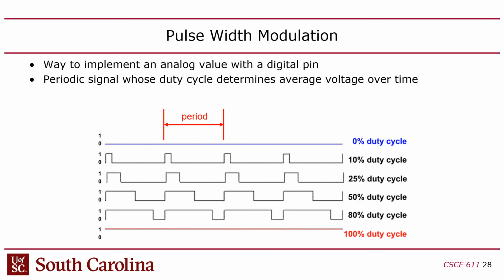And this is used a lot. This is used to control motors, power electronics, voltage converters, voltage regulators, inverters, AC to DC, DC to AC converters, all that stuff. It controls DC motors, it controls brushless motors. It's used also for audio. So if you've ever heard of a Class D audio amplifier, these are the kinds that you would have in, for example, a PA system that amplifies someone's voice. Those usually use this, although they're combined with a low-pass filter on the output. But essentially, they use this switching technique to take a digital signal and make it analog, right?